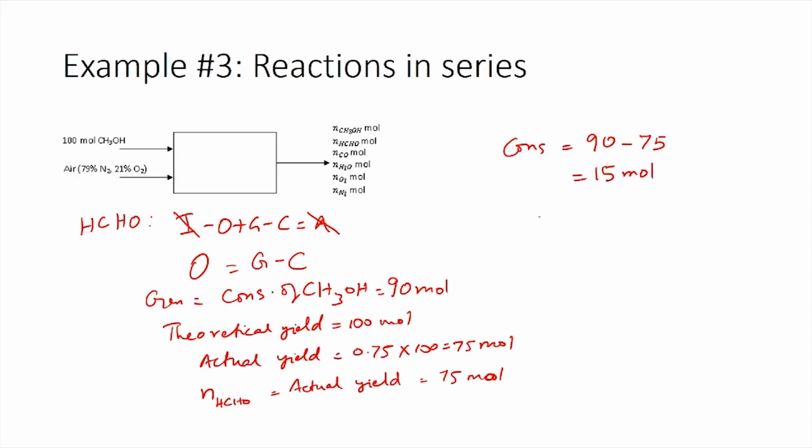So, we can now write a carbon monoxide balance. The carbon monoxide balance would again start from input minus output plus generation minus consumption equals accumulation. Steady state accumulation goes to 0. We would not have any consumption because carbon monoxide is only being produced. There is no input for carbon monoxide, thereby your output is equal to generation of carbon monoxide.